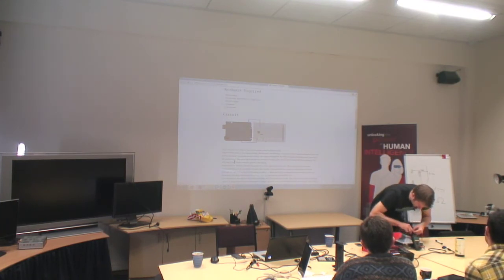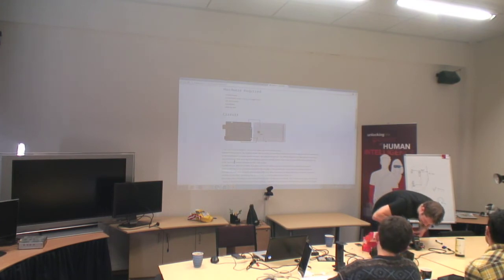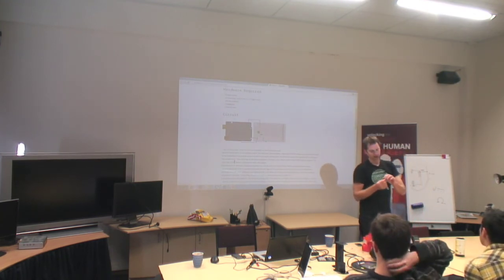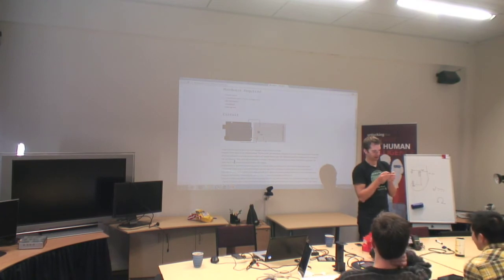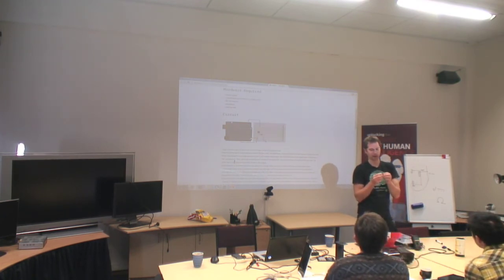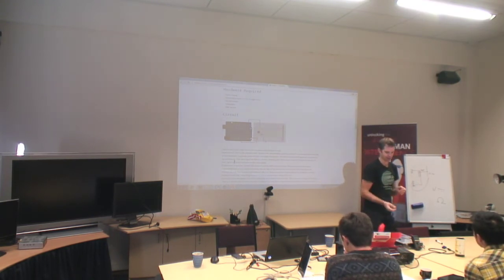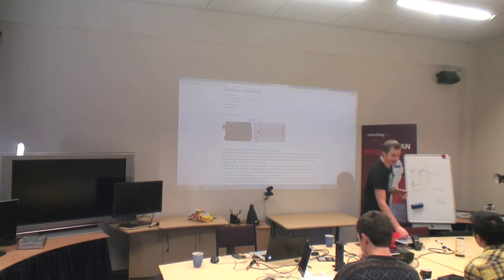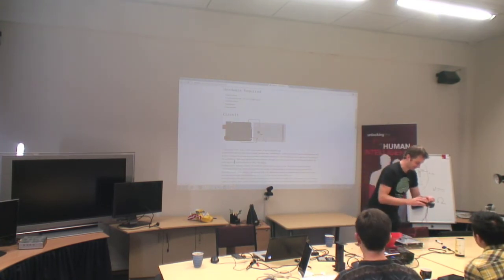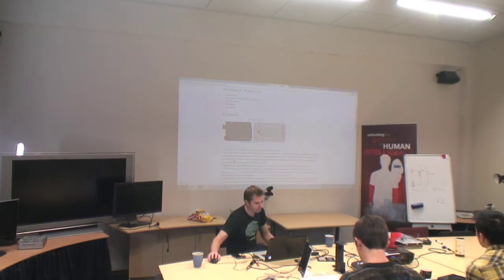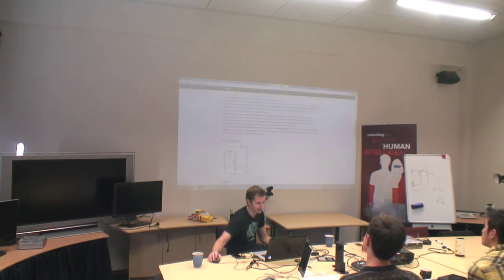But then if I touch the two of those together and push the button in the middle, it'll go down to 0 ohms. When I touch the two legs across the ones which are connected, we get 0 ohms. If I do them diagonally, so the ones which aren't connected, then it'll be as close to infinity, especially if I don't touch it with my hands and it's measuring the resistance through my body. Then when I push the button, it goes to 0 again. Anyway, that's how we figured out which legs were connected to what in the button. But let's have a little look at how the circuit works.